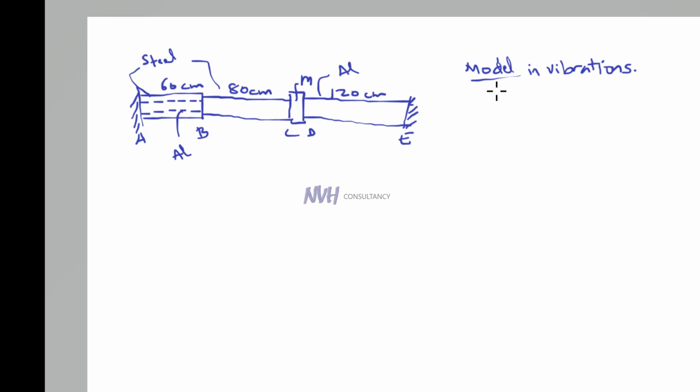By model, what I mean is to develop a mathematical model, you will need to find the torque in every part of this system, as well as the overall torque and the angular deflection, which is theta. The best way to find both is to find the torsional stiffness. So K is the equivalent torsional stiffness of this entire system, which equals the torque over the angular deflection.